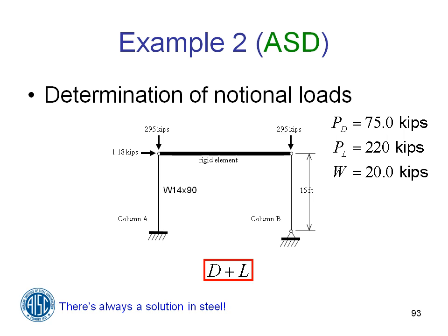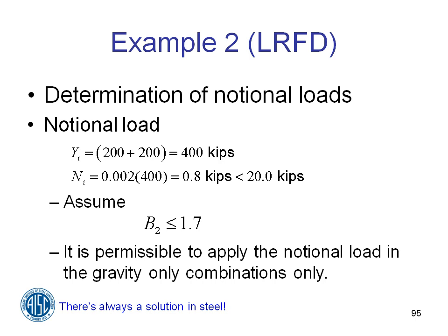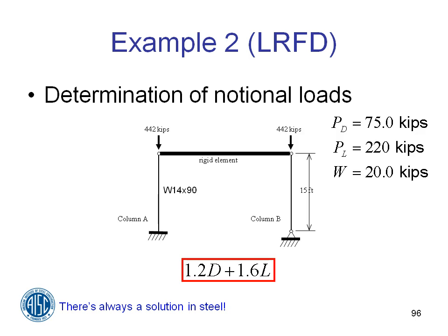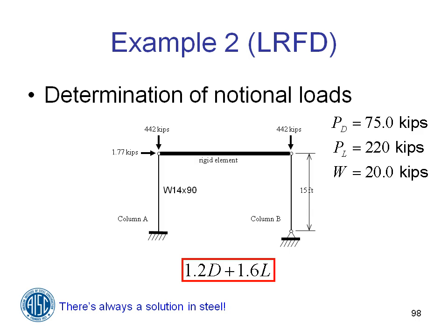If we look at LRFD, the only thing that changes are the magnitudes of the forces. And so you can look at those yourself and see exactly the same thing. So in the gravity-only load combination, there is that 1.18 kip notional load.